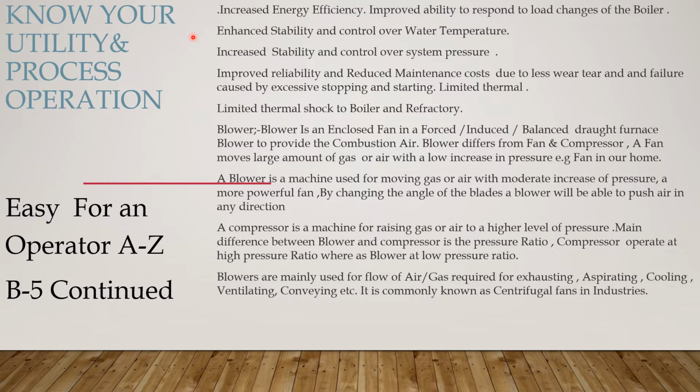So the burner turndown ratio is required in fuel gas firing. Turndown ratio is an important one, and we can have it based on the vendor supply or based on your requirement. Normally, if it is a good burner, the turndown ratio will be 20:1, and you can have this type of benefits. Now we can see another important terminology, blower.